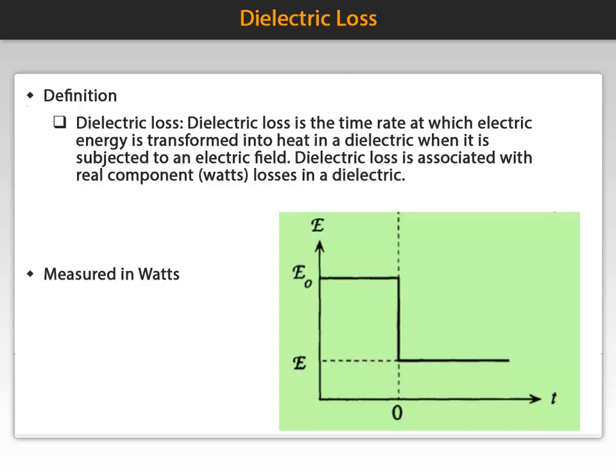The dielectric losses of most insulations increase with increase in temperature, moisture, and corona. Insulations may fail due to the cumulative effect of temperature, that is, a rise in temperature causes an increase in dielectric loss, which in turn results in a further rise in temperature. This phenomenon is self-perpetuating and continues until the insulation fails.